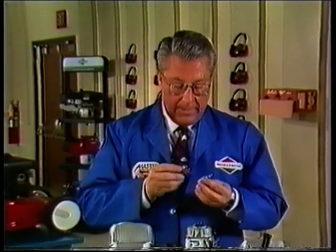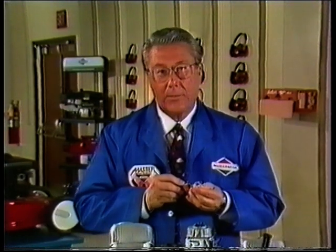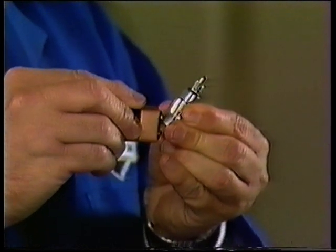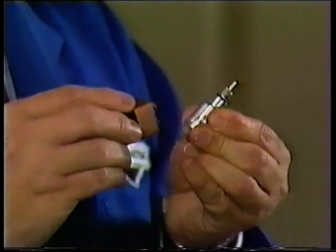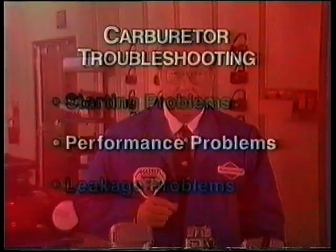Attach one pole of a 9-volt battery to the spade and the other post of the battery to the solenoid case or black ground lead, if there is one. If the plunger activates without sticking, the solenoid should be considered good. Finally, be sure to check the main jet of the carburetor for debris. This can cause the engine to appear to be under-choked and, in some cases, can completely stop fuel from flowing into the combustion chamber. As you've seen, a number of factors can cause starting problems. While choke operation is common, it's not the only answer.